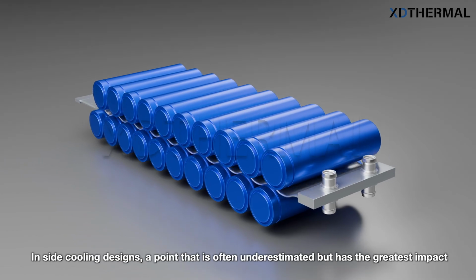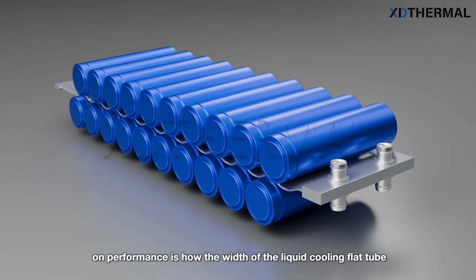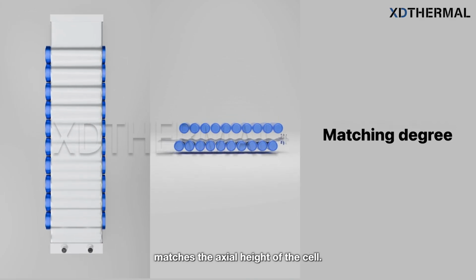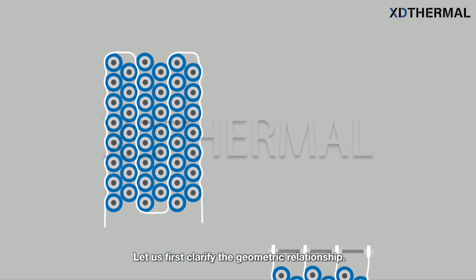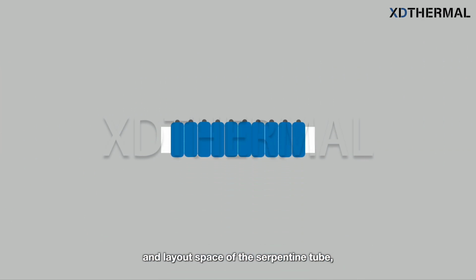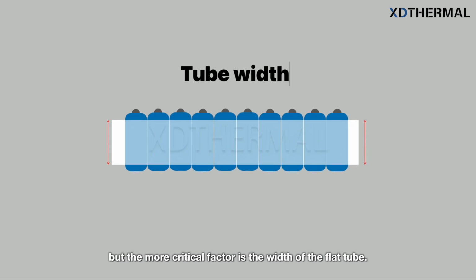In side cooling designs, a point that is often underestimated but has the greatest impact on performance is how the width of the liquid cooling flat tube matches the axial height of the cell. Let us first clarify the geometric relationship. The cell diameter mainly affects the bending radius and layout space of the serpentine tube, but the more critical factor is the width of the flat tube.